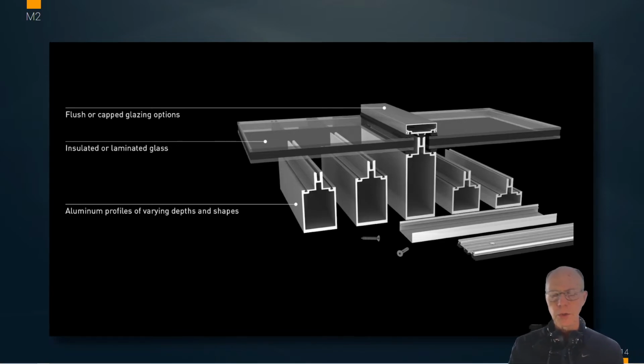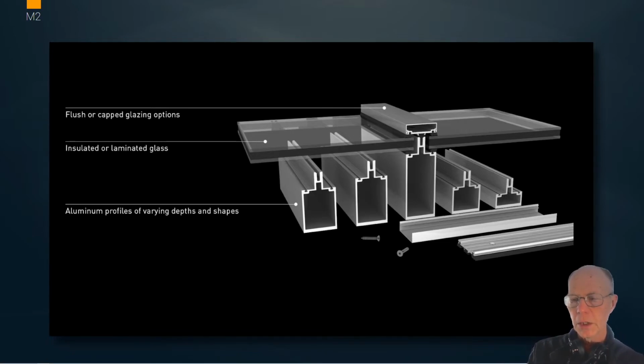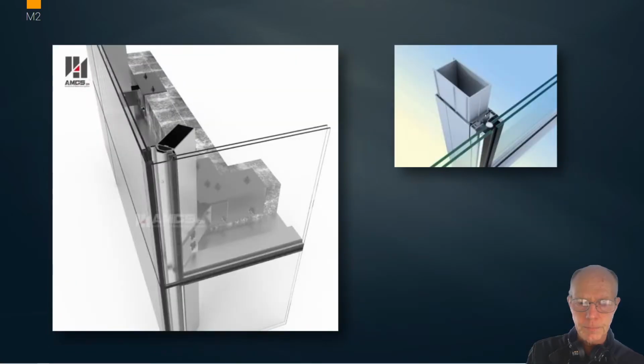Once again, just so you can visualize it, I think after looking at the drawings and back to this again, two pieces of glass, this idea that this is the finish cap, so this is the outside. The depth of the system is typically towards the interior of the building. In this case, by varying this depth, you can change the strength of the wall to resist loads on it, wind loads or whatever might be imposed upon it.